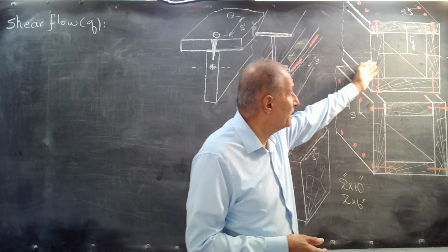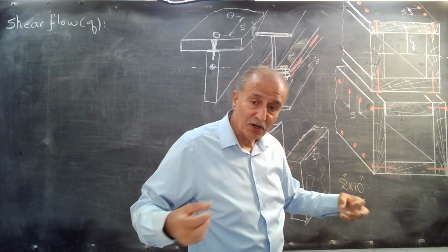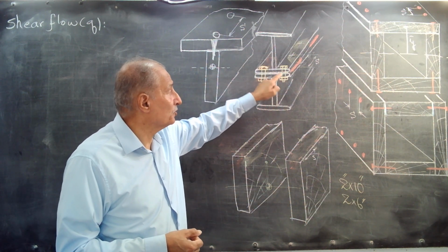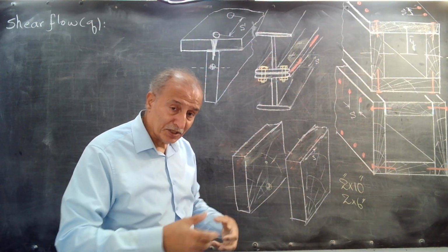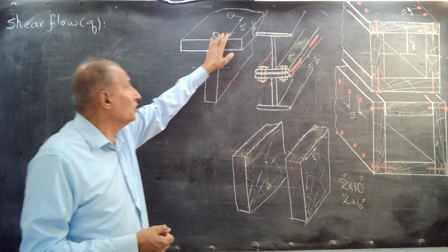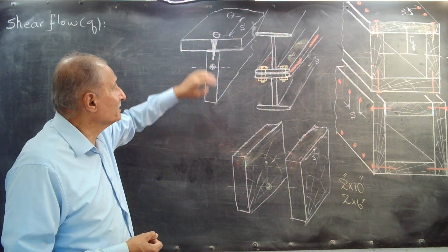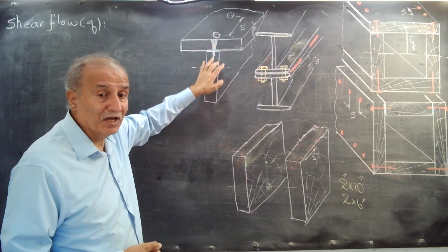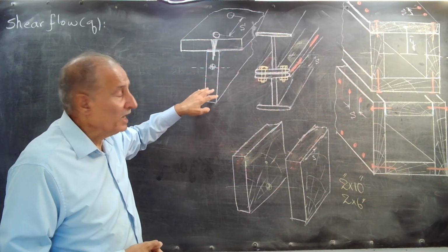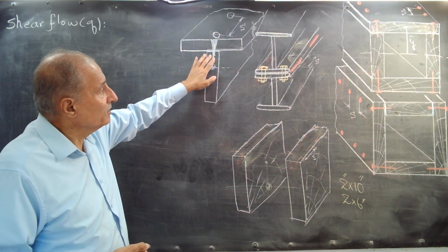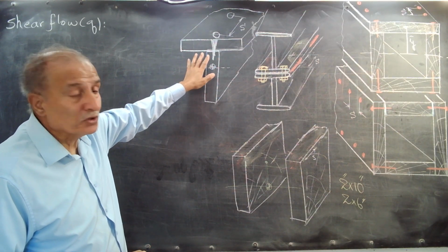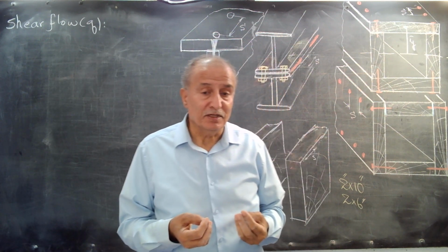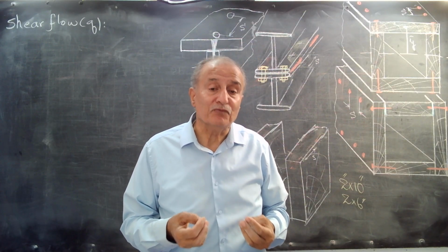For example, 4 joists are connected together to make one beam, or 2 I-beams are connected together by bolts or by welds to make another, stronger beam, or 2 lumber, timber or wood planks, or maybe welded if they are steel, are joined together to make a T-beam. In this case, we need to know the fastener that we use to connect them together, how many of this fastener we need for our design, and how much the space between them must be.